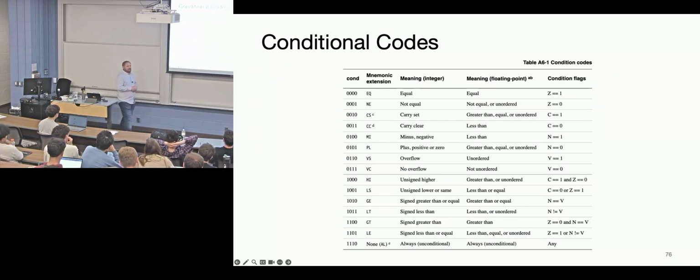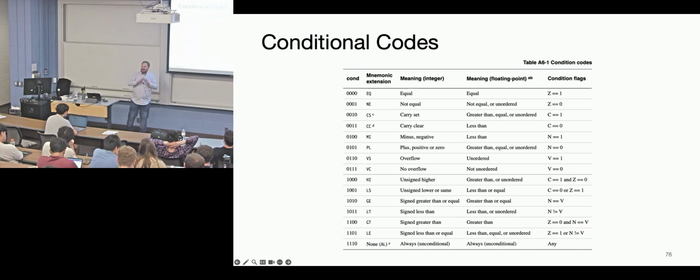Normally that doesn't really matter, but I had one case in my research where it made a huge difference. So at least being able to access those flags. Me and my buddy were working on that WISP project, the RFID tag that had no batteries and ran a full microcontroller. We had a very challenging timing constraint where we had a bit stream of data coming in, so basically edges, and we had to count whether it is 1 or 0 in a certain time frame, and we ran out of registers. We had eight 16-bit registers, that's all we had. We ran out of room. We didn't have enough time to store it into flash. We had to keep track of one piece of information.